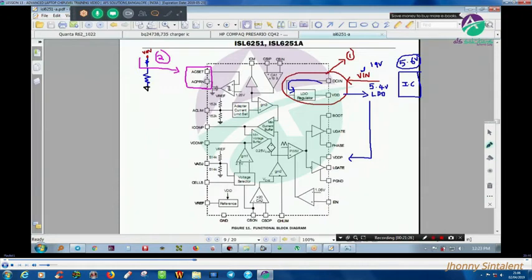This is my second important confirmation which has to come. When this voltage comes, it will be around maximum 3.1 volts at the highest, depending upon the motherboard. I have seen 3.1 volts as the highest. It can start from 2.4 to 3.1 volts at the highest. If it is 3.2 also, it will not work. There is a problem in this resistor voltage divider.